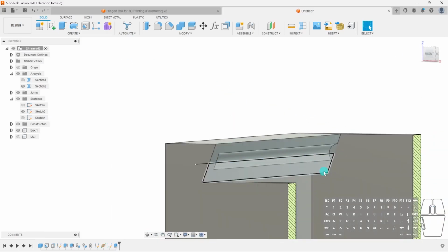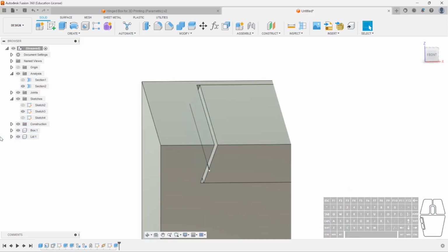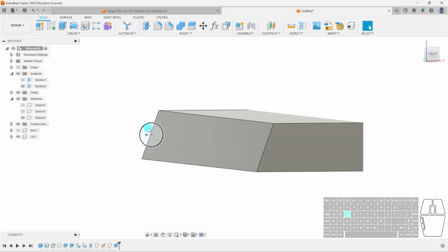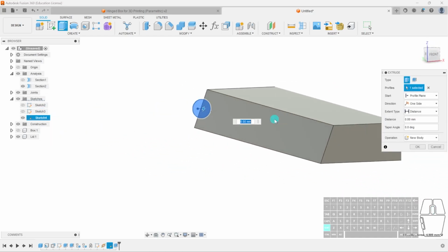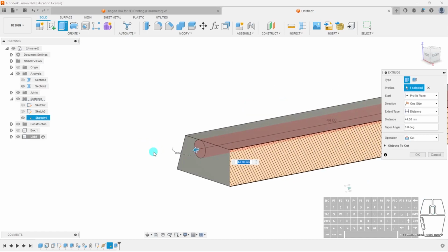And so with that, I can always make a complementary face to my lid. So I'll put it here, show my lid. I don't need to show my box. I will bring up my previous sketch here, which is a circle. And now if I select that circle, you can see it's still on the face, that's fine. I will again bring it back up to here. And again, remember I didn't actually go there. So instead of doing that, I can always just drag this back out.